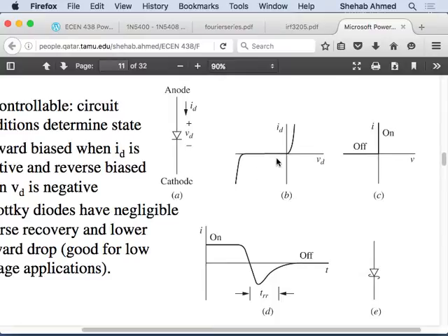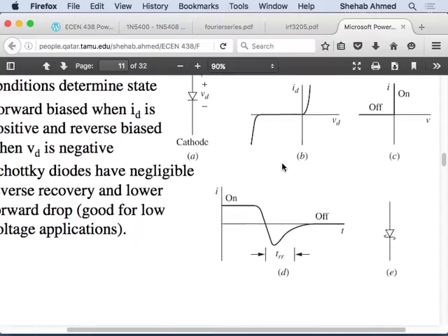First we pick the topology. Do I care how much power loss is in this device? No, not yet. I will put an L, I put a C, I put a switch, I put a diode, but I didn't pick it yet. I just put it there. Then I have to go and pick it. For me to pick it from the data sheet, I will have to utilize the real IV characteristics. Okay, so that's the development stage here.